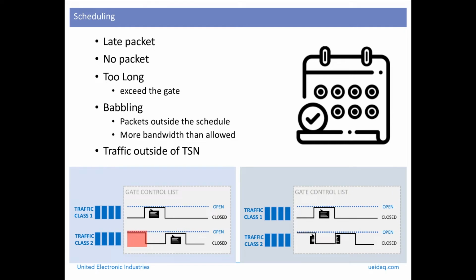Another good test is a packet that exceeds the gate length. Again, this would normally be handled by the switch, but really you are trying to look at failure modes in your device and not that switch. In 1553 testing, we often are used to simulate babbling on the bus, an undisciplined device. We should be able to simulate the same in a TSN system. What does it do to your device? How is it affected?